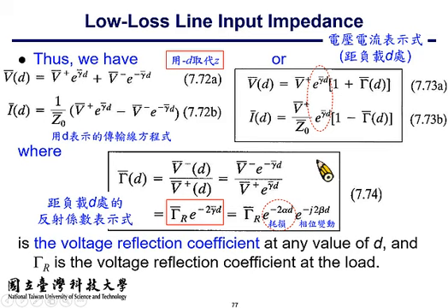So the reflection coefficient gamma becomes favorable and meets the specification. Well, of course that's cheating, right? Once you know the principle of the transmission line, you know that the good reflection coefficient level is obtained in terms of the loss on the transmission line. It's not that the antenna itself may not be pretty lousy, right? Okay.